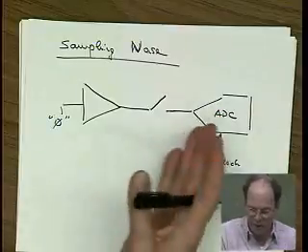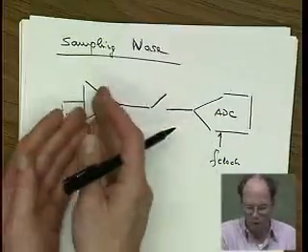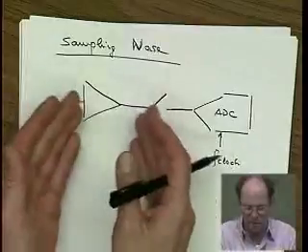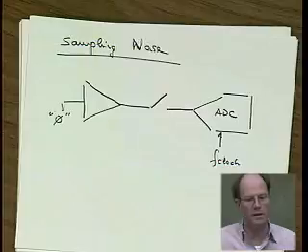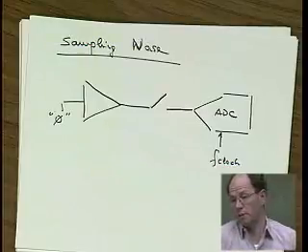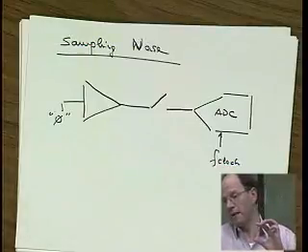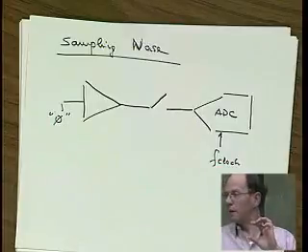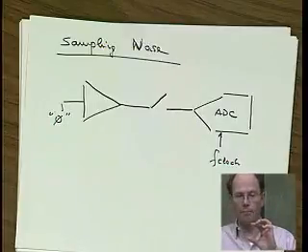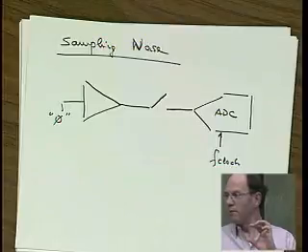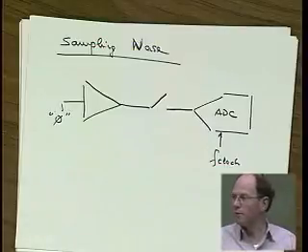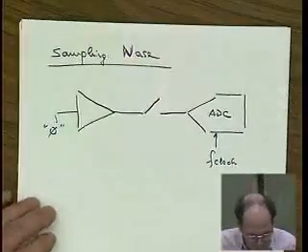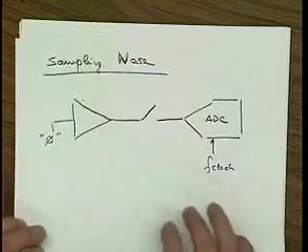Because ultimately, this is what we want to know. We don't want to know what is the spectral noise density coming out of this thing. We want to know how big these noise samples are, so we can compare them to an LSB, for example, right? If the LSB of our A to D converter is, let's say, 5 millivolts, and our noise samples are 10 millivolts variance, well, we know we've got a problem. Our A to D converter converts a signal, and it also converts a whole bunch of noise. Okay, so we have to calculate what the variance of this sampled noise is.